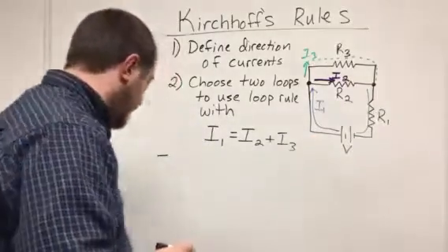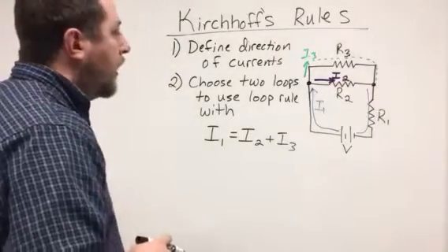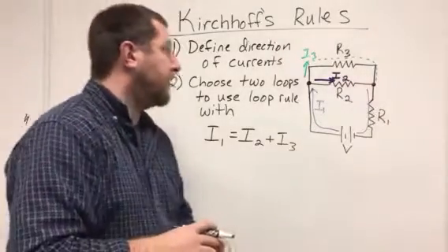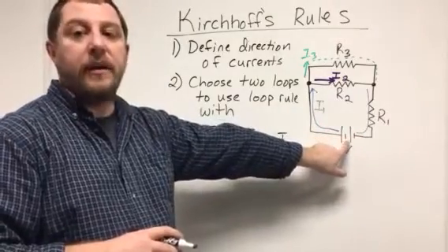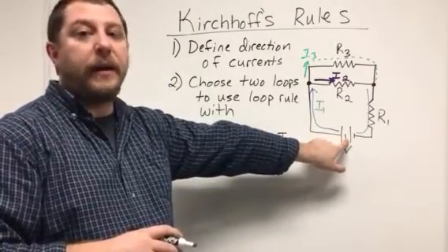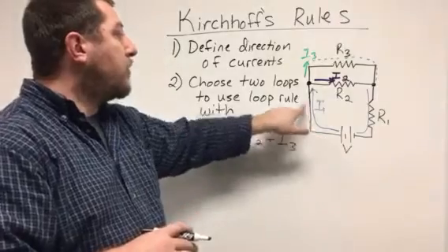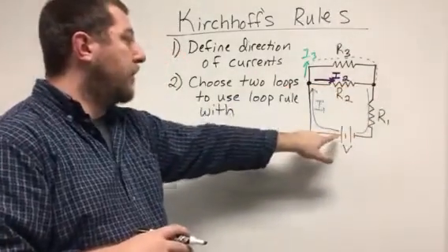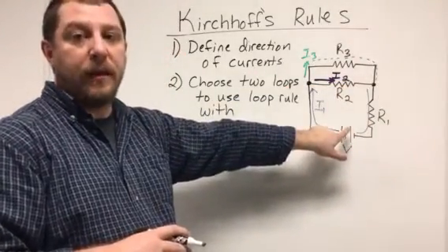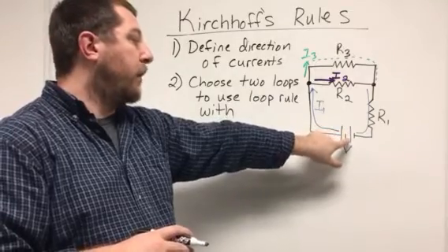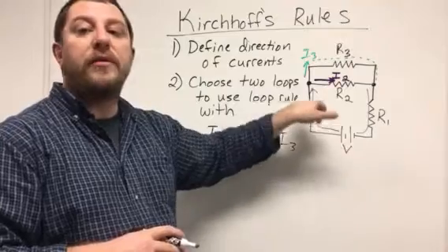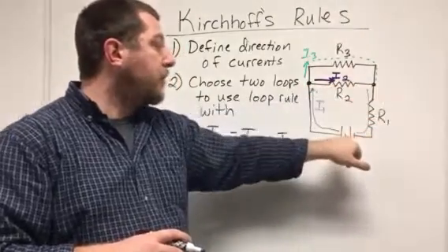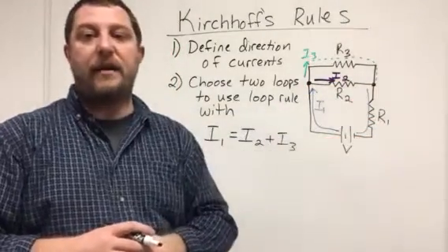It'll actually be easier just to show you instead of trying to write these down on our confined space here. So what you do is you choose an element in our loop. I typically start with a battery, and then you go around that particular loop until you come back to that particular element, all right? So whatever element in a loop you want to start with, you start with that element, you go in a particular direction, and you come back to that element.